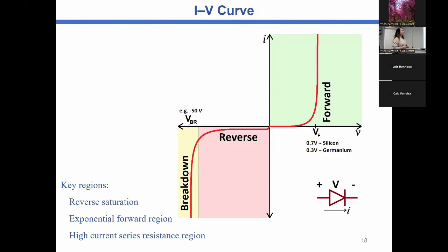And this is quite interesting because after a certain amount of energy, of potential, that in silicon, for instance, is 0.7 volts, in germanium is 0.3 volts, after it we have an abrupt current. This abrupt current comes from the minorities and also the built-in potential getting to a flat-band condition and allowing the minorities to move freely, and also the electric field pushing and pulling, depending on the